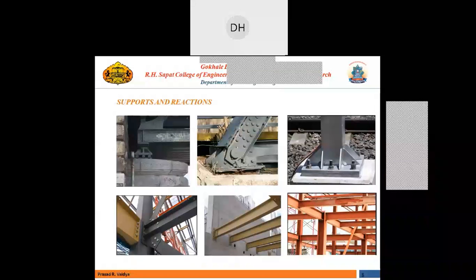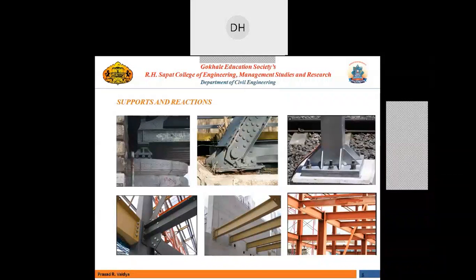So steel structure wise, if you ask me, for industrial buildings, there are two connections. One is shear and one is moment connection, right? So for a moment connection, you should have the flanges of both of the beams, either with the beam or with the column, connected to each other with the help of a cover plate. Then only is the moment transferred from flange to flange. Then that is categorized as a moment connection. Otherwise, it will always be a shear connection, right?